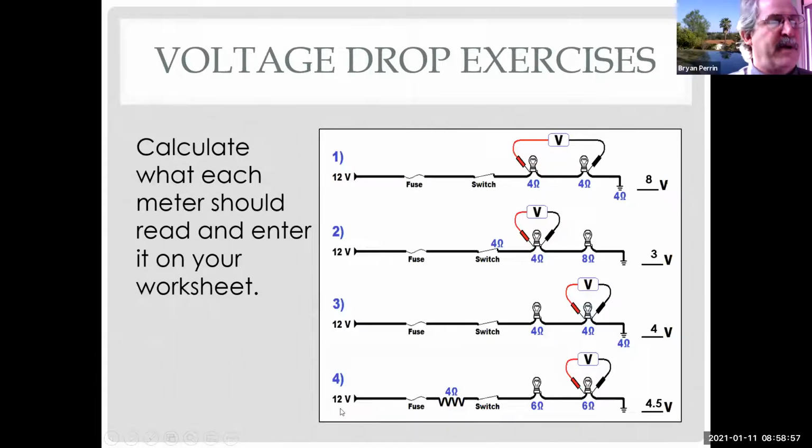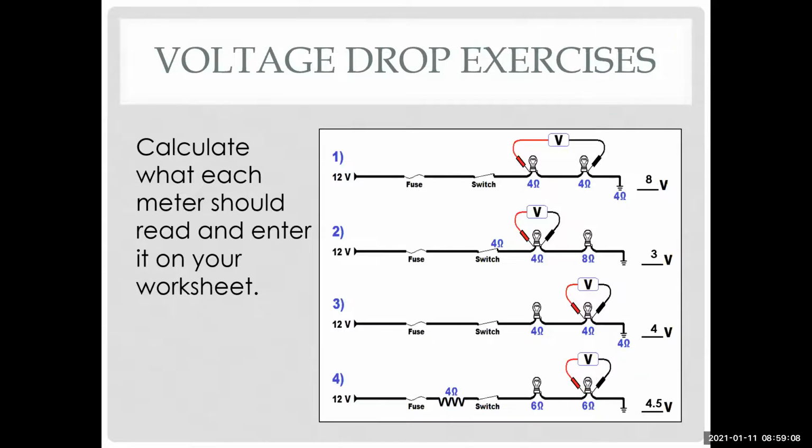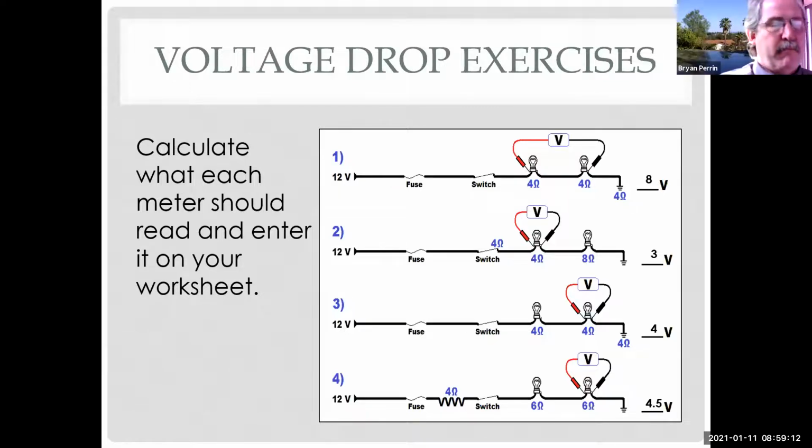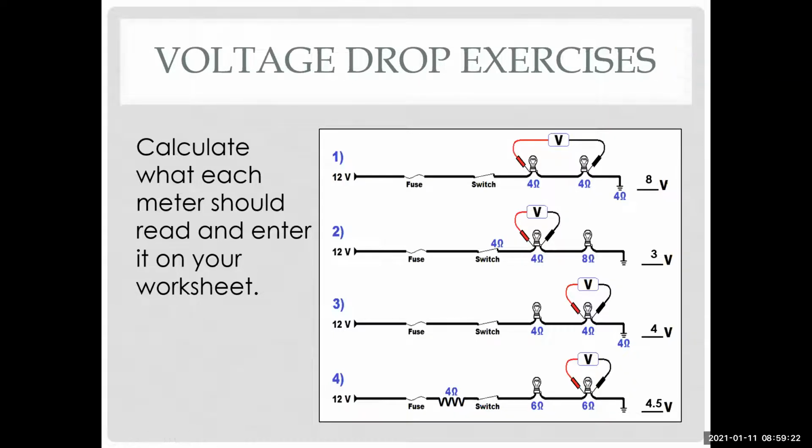Voltage divided by resistance will give me current flow. If I reduce that down, I can make that 3/4, right? Or I can just do the math with a calculator and come out with 0.75, either way. So if I take 0.75 times 6, which is the only resistor I'm testing, I'm going to come up with 4.5. All right. Got it.